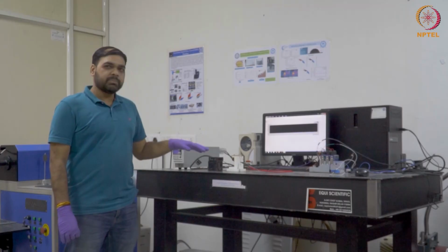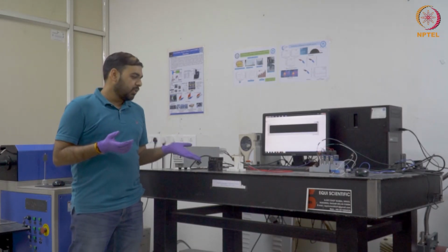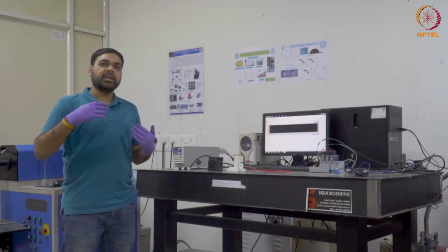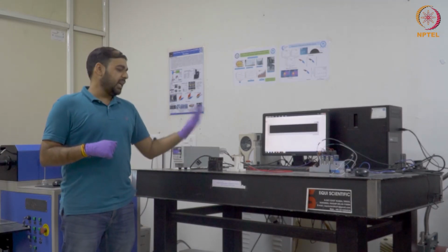So this setup is used to study the bimorph for electrical actuation for a number of cycles. Let's say we use it for 1 lakh to 2 lakh cycles up to the failure, where either the thin film which we have deposited gets delaminated, or we are getting a burning of the film. In that case, actuation of the film stops, and there we can say we have studied the life cycle of the bimorph structure.